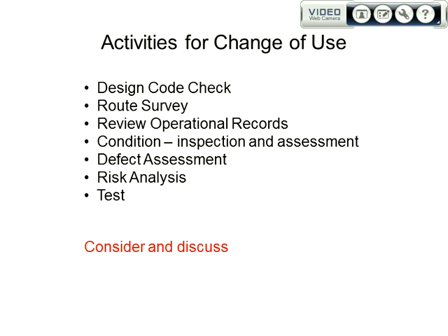You've got to do a route survey, as we've considered ad nauseum. Pipelines are routed in third-party land and they're accessible by the public. So you can't just say we're going to change the use of the pipeline without having any idea at all where it is and what's around it and whether anything that's around it is going to cause you problems. That's why I've given you the route map and the aerial. The route map has got the detailed aerial photographs superimposed on it so that you can interrogate that.